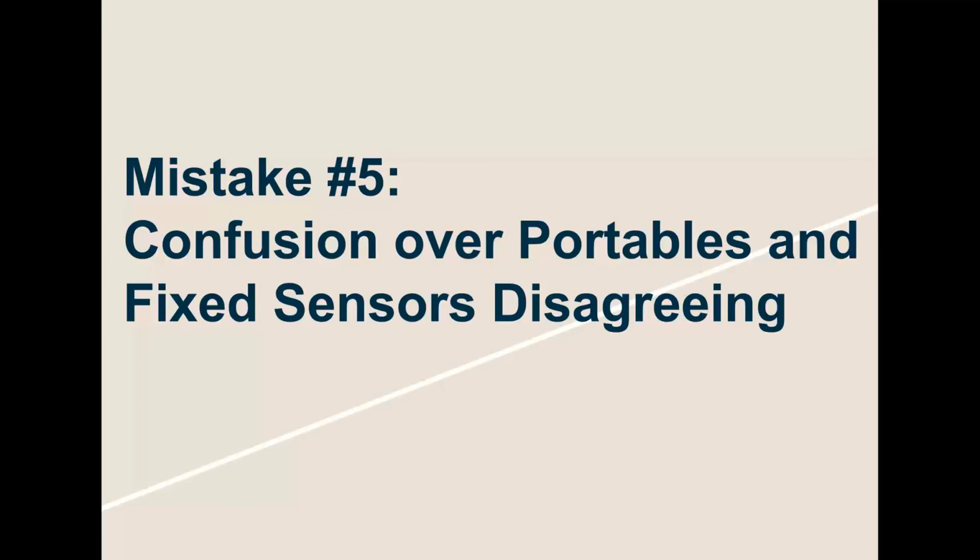So if you calibrated your portable correctly, but you're not calibrating your fixed gas detector correctly, the fixed gas detector will react a lot faster and a lot more because its gain has been turned up. Whereas the portable, it's not, it's normal, let's say. And vice versa, it goes the other way around too. So you have to really, really understand and make sure the type of calibration equipment that you're using. Another example, for portable gas detector, you could do a zero calibration in fresh air, right? You take it outside and you do your zero in fresh air.